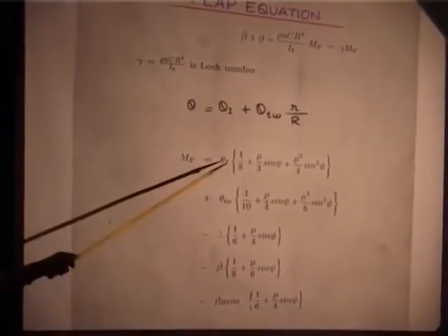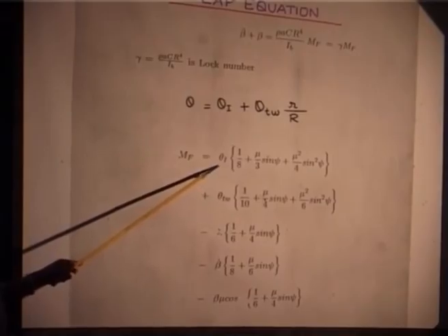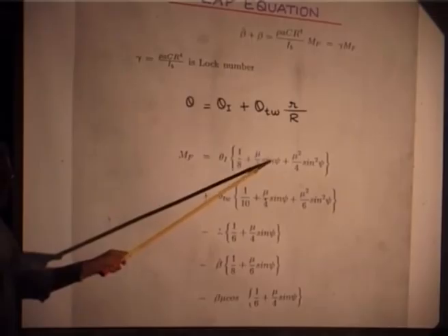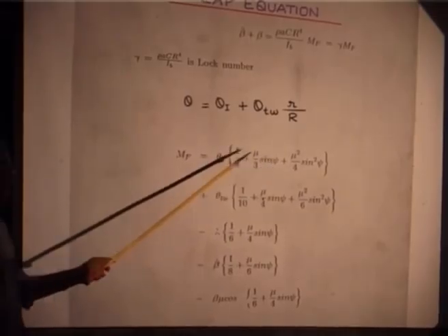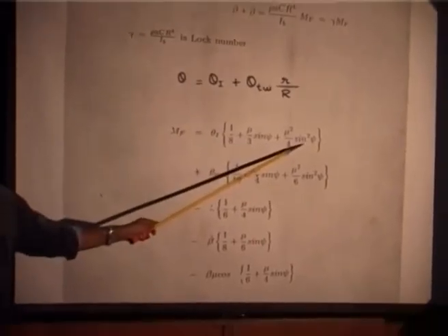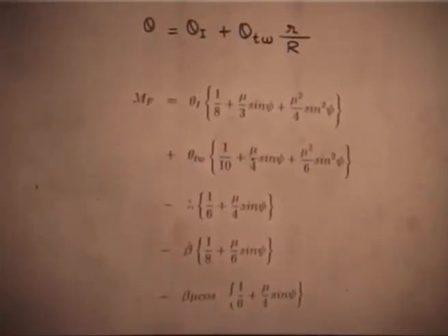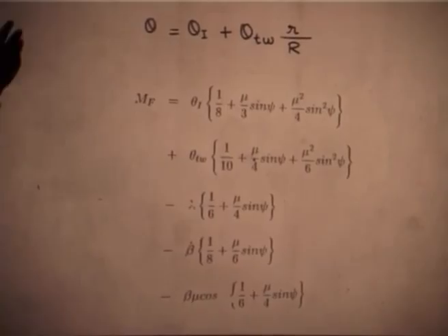Because if I put theta I equals theta naught plus theta 1c, theta 1s times sin psi, cosine psi, this is getting multiplied with another sin psi, getting multiplied to give sin square. That means I am having the second harmonic, third harmonic, everything comes as an input. So my response also will have all the harmonics.